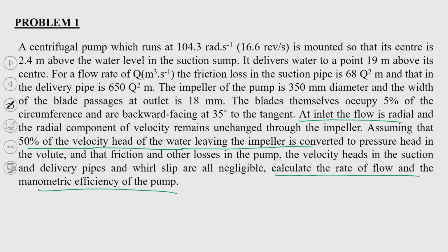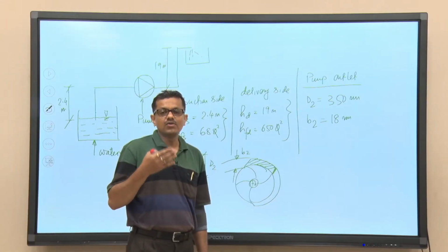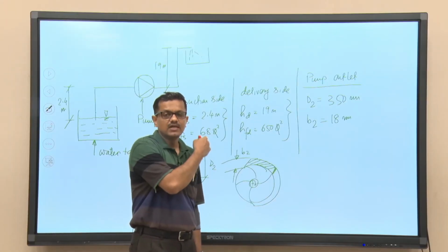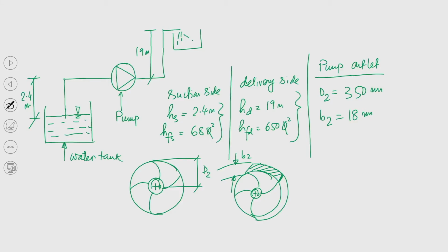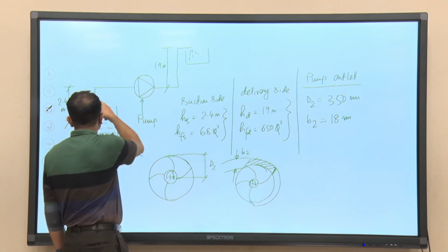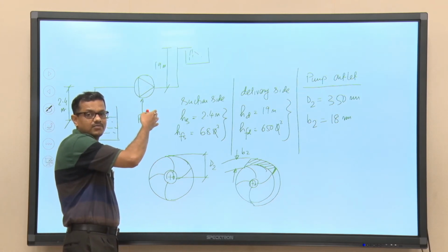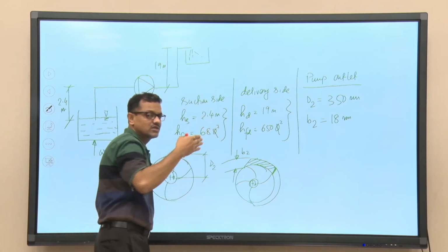So, we can now go to the slide wherein we have drawn the schematic. You can see now the first objective should be, can we quickly calculate the amount of head that this pump needs to develop. This pump is installed in a pumping station with the sole objective of developing pressure. So, liquid will be transported from this place to that place, and we need to overcome the static height both on the suction and delivery side, and you also need to have some amount of velocity at the discharging point.